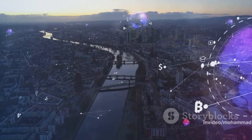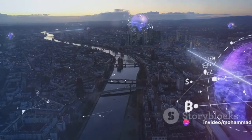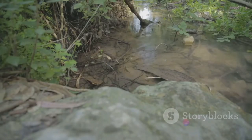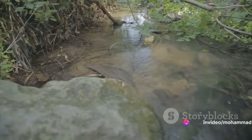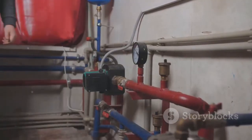Now, let's put this equation to work to better understand it. Imagine we have a flow rate of 90%. Using our equation, this would yield a differential pressure of 81%. This is due to the fact that the square of 90%, or 0.9, is 0.81, or 81%. The mathematics here is simple, yet it's crucial in understanding the relationship between the flow rate and differential pressure.